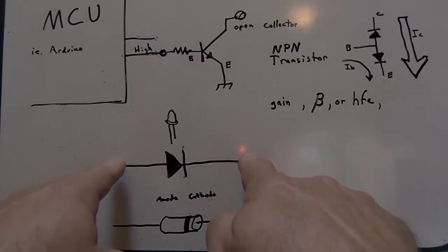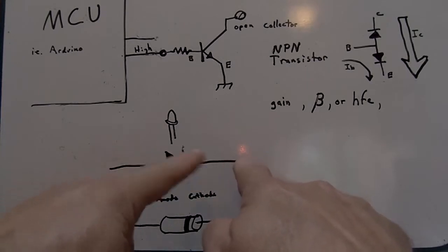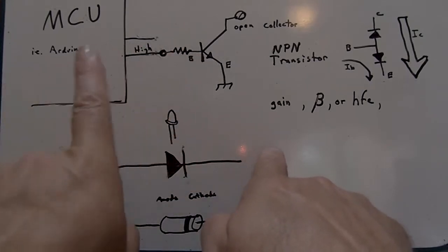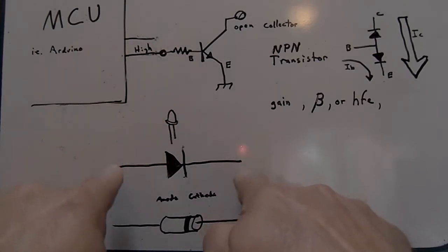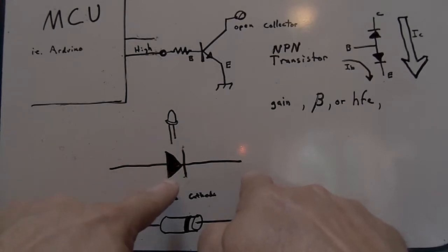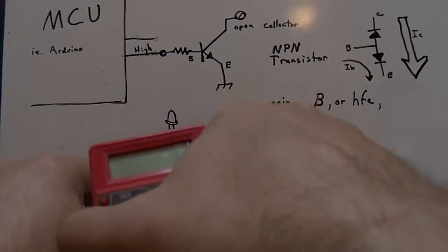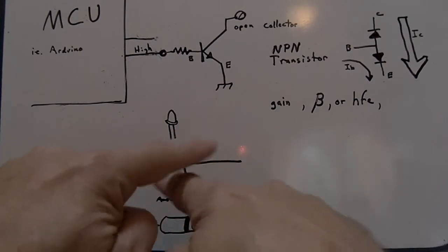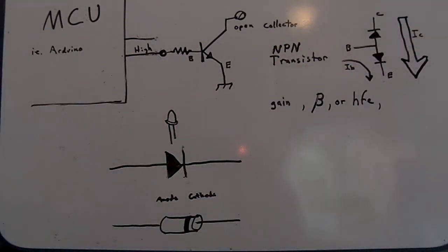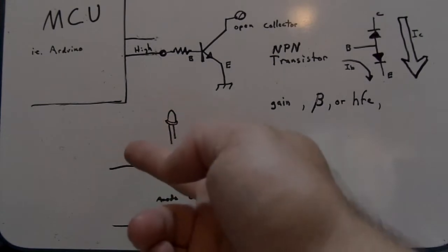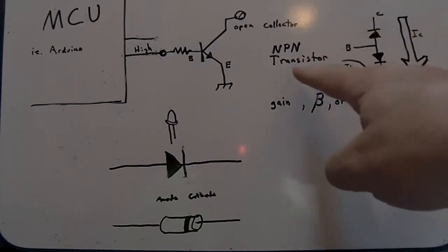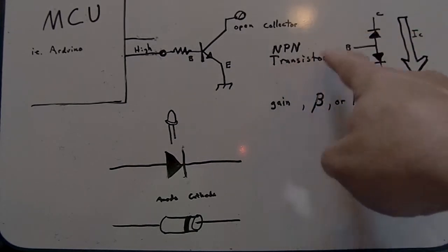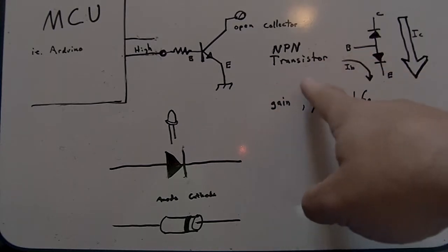So normally you'd put the positive lead there, negative lead there, you'd lose a certain amount. Normally in an analog meter you get about half current flow, about a half reading. Many meters have a special diode mode, and they'll read like a half volt on a digital meter. You'll see that 0.5 I was telling you about when you're forward, and when you're negative it'll give you some kind of indicator. So that's simply testing a diode one way, then testing it the other way. You know it works, and which way it works. A transistor can actually be tested the same way. For the example of an NPN transistor, which is the most common transistor around, they're a little cheaper and more readily available than a PNP or a FET.